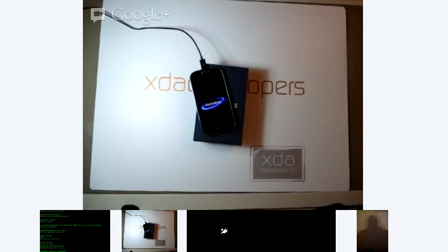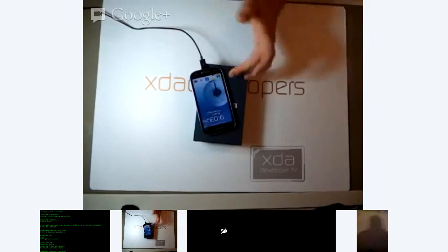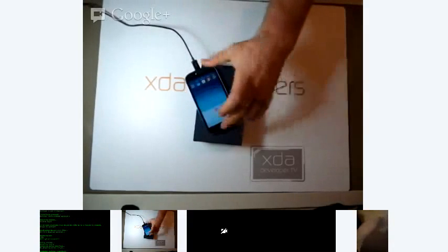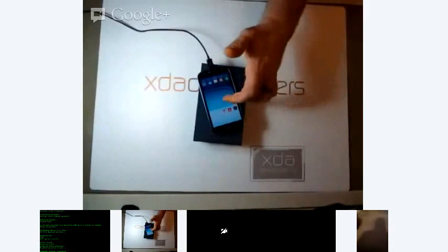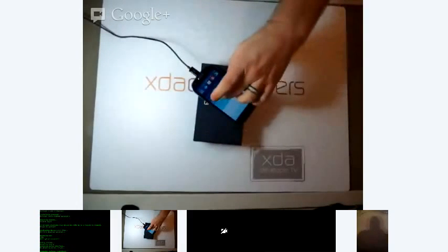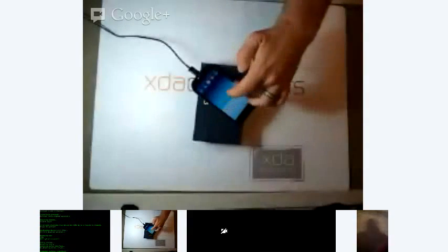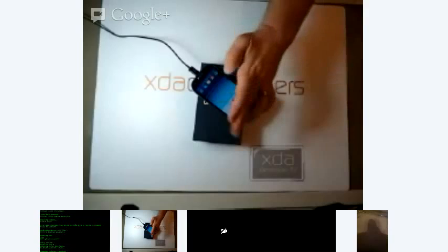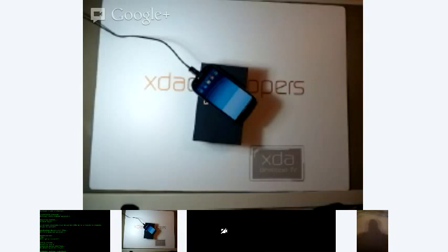All right, there you go. Now you notice that it's kind of jerky now. It's actually sending all of the UART output, and there's a ton during the boot sequence. Now, because it's sending so much output, it's actually locking up the processor a bit, trying to get all that output out of the buffer. So it's a little bit jerky on the startup, but other than that, there should be no real difference because it's basically just sending the dmesg outputs to the UART port.